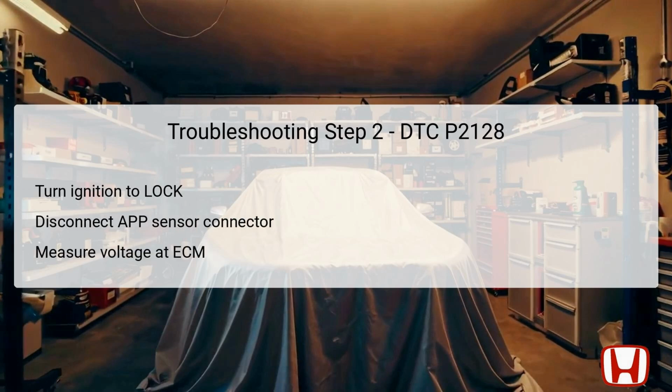In this step, the focus shifts to determining the specific area of failure. Start by turning the ignition switch to the lock position. Next, disconnect the APP sensor's 6P connector. Once disconnected, turn the ignition switch back to the on position. At this stage, you will measure the voltage between the designated test points.